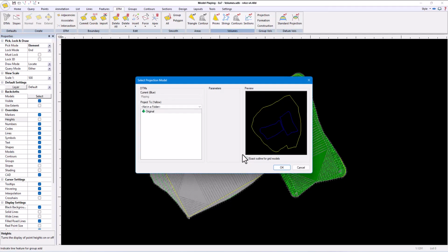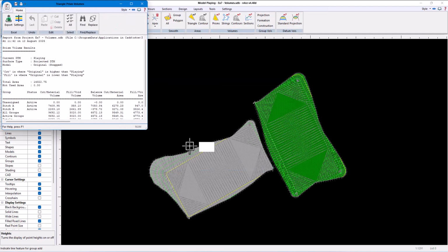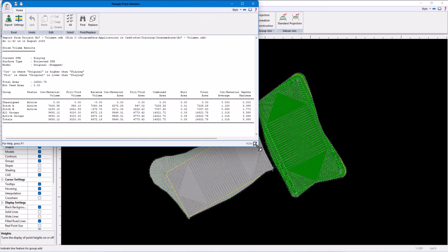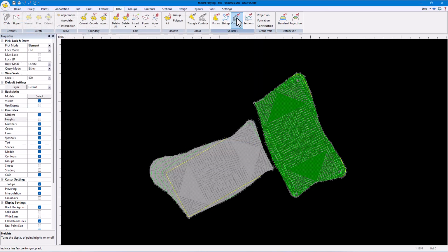The volumes are now much more accurate, but obviously do not balance. Pitch A still generates a large excess of material that cannot all be used up in the building of Pitch B, even though it required more material than it excavated. We therefore need to raise Pitch A and lower Pitch B. The degree by which we need to do this is what we now need to determine.